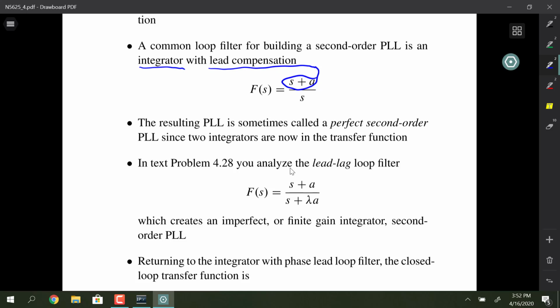The overdamped situation is where the 2 poles, due to the second order system, are on the real axis. Critically damped is when the 2 poles are on top of each other, and underdamped, if you remember from circuits, is when the poles are complex conjugates of one another. So they're sitting in the left half S-plane. That's the situation we're going for. If I draw the S-plane here, sigma j omega, we're going for that situation where we have a complex conjugate pole pair.